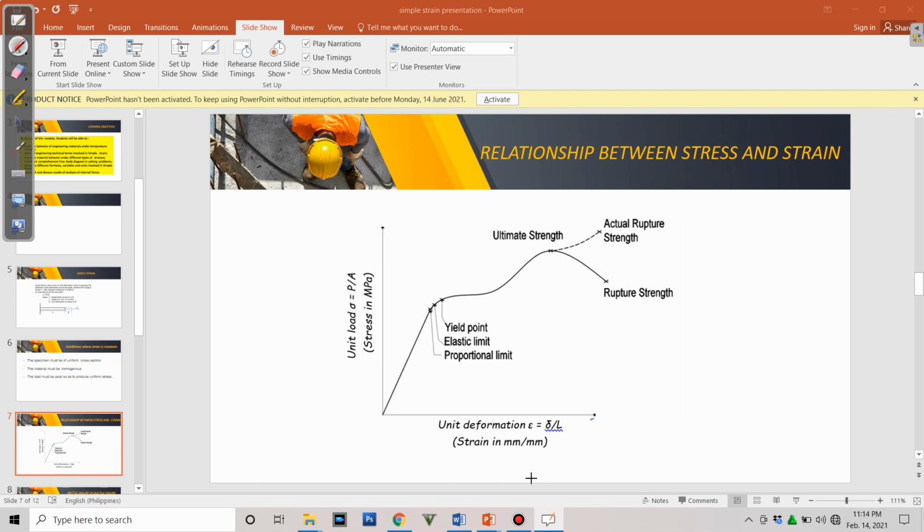Next to that is the elastic limit. Beyond the elastic limit, permanent deformation will occur. The elastic limit is therefore the lowest stress point at which permanent deformation can be measured. This requires a manual load-unload procedure, and the accuracy is critically dependent on the equipment used and the operator skill.